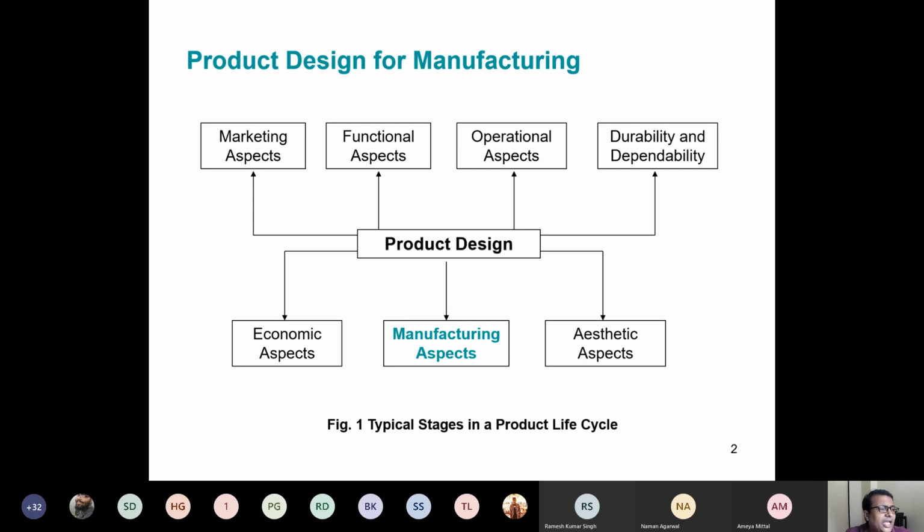Cost versus performance plot. But okay, but how do I choose what performance I want? What drives my performance? If it is some performance index, tolerance range is, you have to decide that, right? Because tolerance range is driving the price. If I take the tolerance of plus minus 1 mm, it's almost, as I said, 600 rupees. If I take plus minus 1 micron, the cost is tens of thousand rupees. So tolerance I have to choose somehow, right? Performance index, I kind of get it. More tolerance will give less performance.